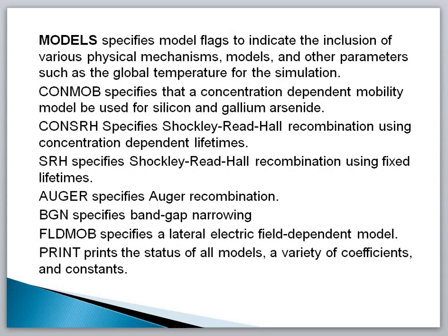Next, you have to define the model statement. Models specify model flags to indicate the inclusion of various physical mechanisms, models, and other parameters such as global temperature for the simulation. Different syntax is used for the model statement. First one is CONMOB, which specifies that a concentration dependent mobility model be used for silicon and gallium arsenide.